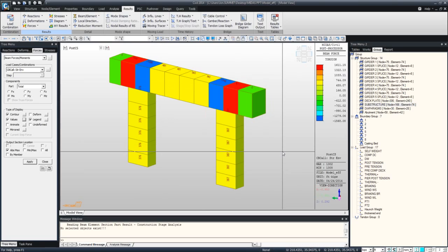To put that into reinforcement perspective, that allowed us to go from number 7 stirrups at about 3 inches to follow the ACI torsional provisions to number 5 stirrups at about 9 inches to follow those same provisions for torsion. From seismic demands, the bent cap reinforcement turned into was more heavily reinforced. However, just for the torsion, it was allowed to be reduced.